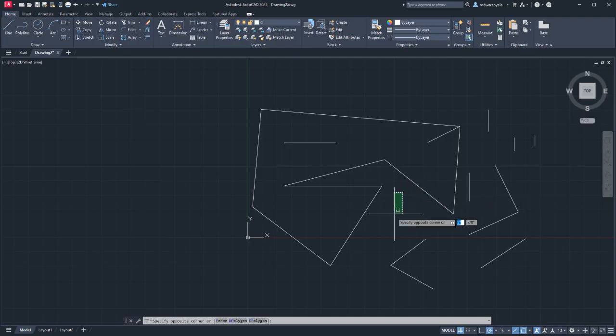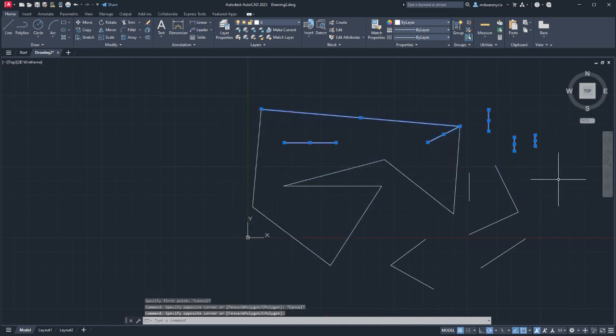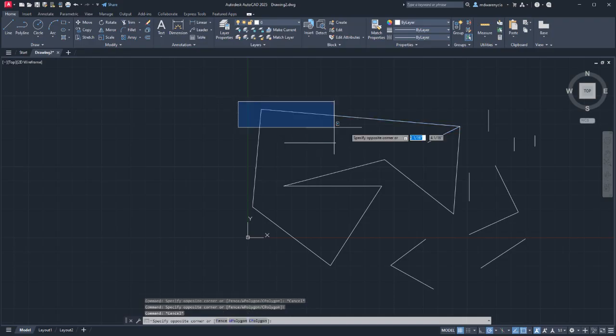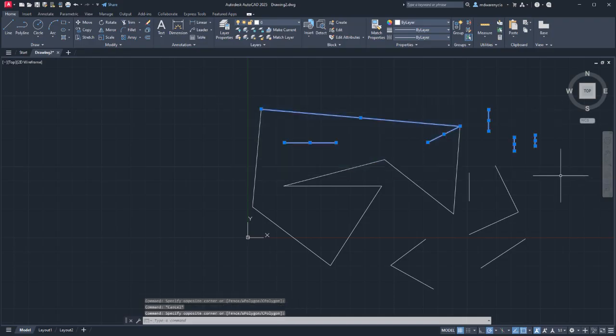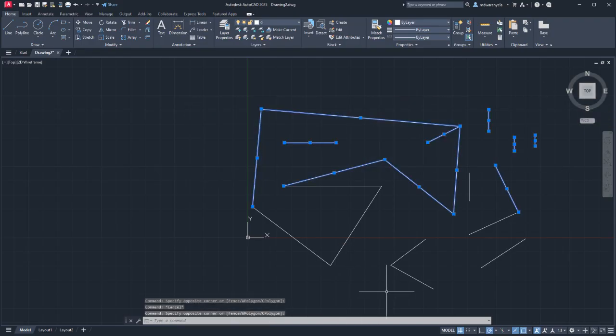So right now I did this selection. You can see as I go different directions, this color changes. This blue one will only select things that it fully circles. So if I do a selection like that, I only get these ones up here. All right, so I'm doing a left to right, and it only gets the things it fully circles. If I do right to left, it's going to grab everything it touches.